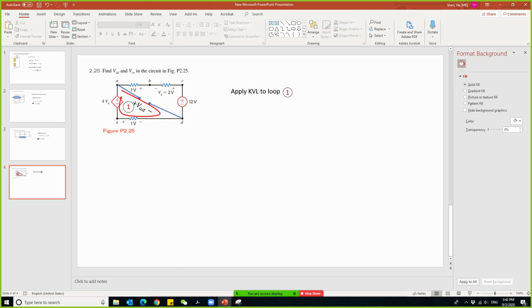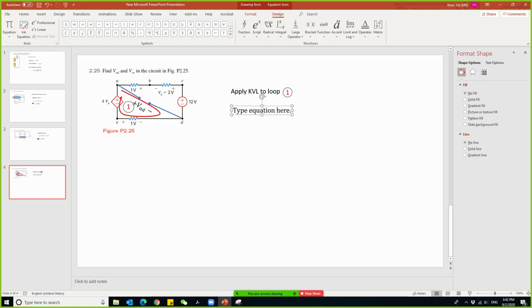We'll write the equation. We count the voltage drop by following the loop that I defined, right? The first drop from A to D is something we're looking for, VAD. And from D to E, that is -1, right? Because this is from the lower to the higher. So you can also see it by using the sign that I first see.